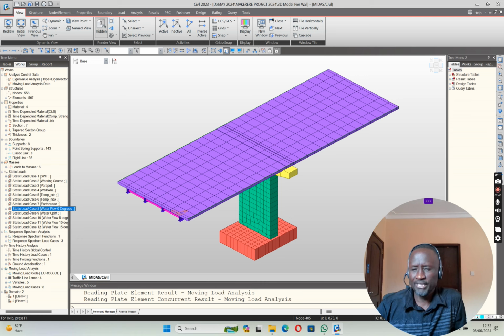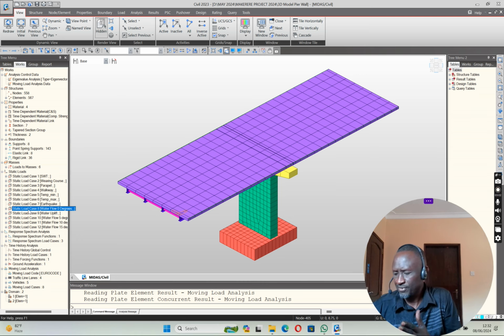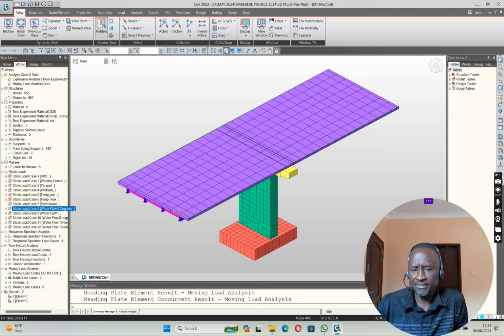They are trying to avoid water hitting the deck and the pier at an angle. Definitely you are subjecting your deck system and pier system to a lot of force from water. So normally you have to align your pier support in the direction of flow. So water comes and creates a stream kind of flow, like the way you have the airfoil when it is moving through an object being blocked. It comes and creates vortices at the back. So the way you do your aerodynamics is the same thing.